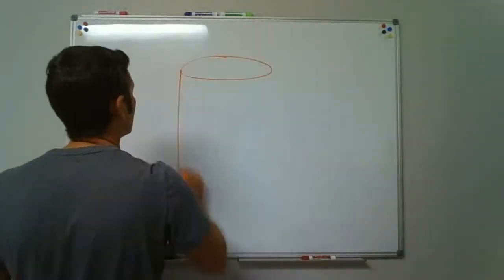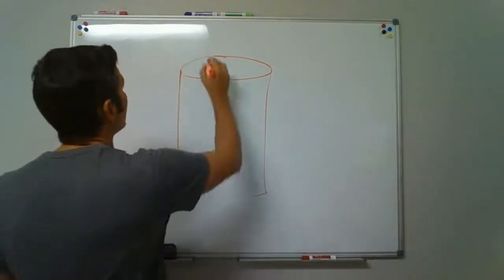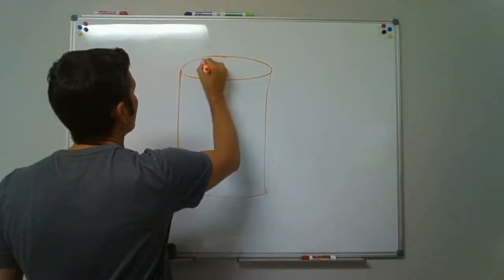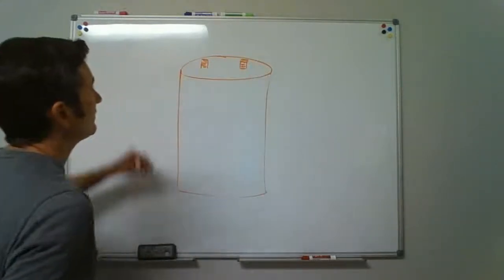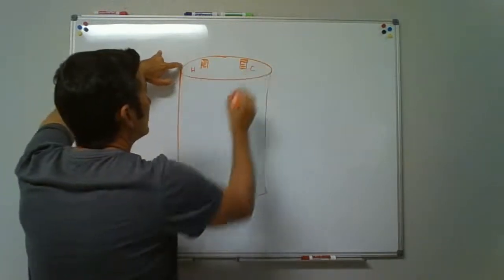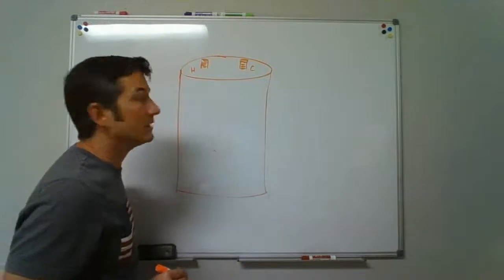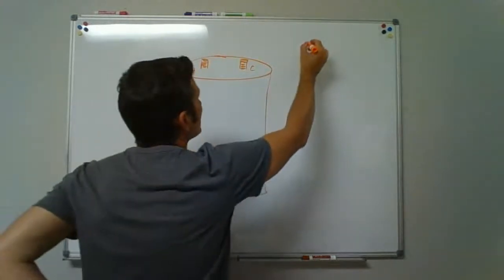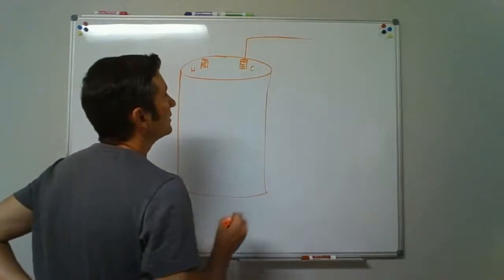Here's your water heater. What you've been putting in has these nipples up on top, 3/4 inch threaded male nipples coming up. You've got a hot side and a cold side. This is a top fed water heater, meaning we take a cold water line and attach it to the cold here.